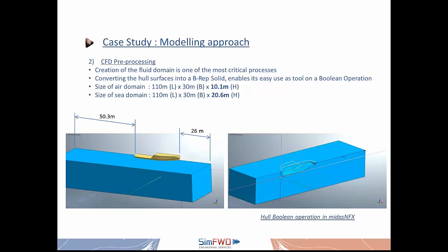So you can see that after we have our BREP solid hull and our BREP solid domain, we can subtract by a Boolean operation the one from the other, and thus create the fluid domain.